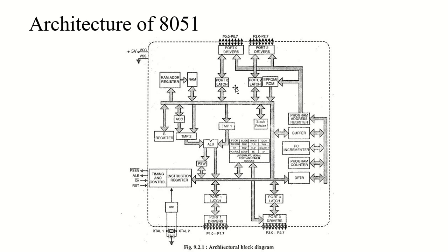Once the input output device has been serviced, the microcontroller resumes the operation from the point where it had stopped. So the external asynchronous input applied to the microcontroller is termed an interrupt.